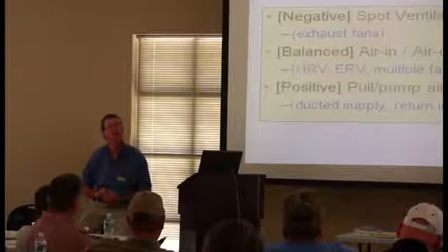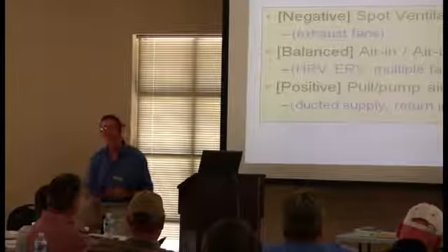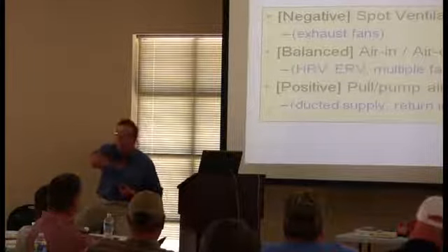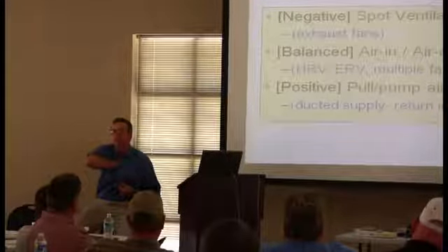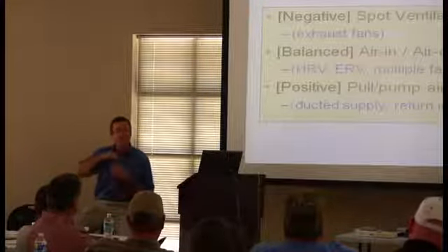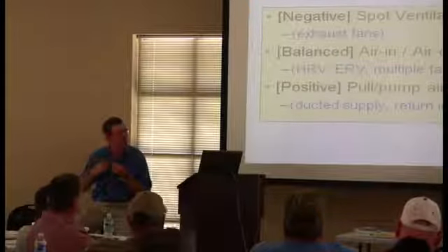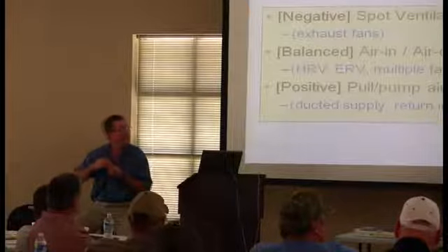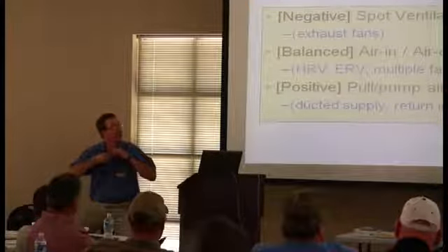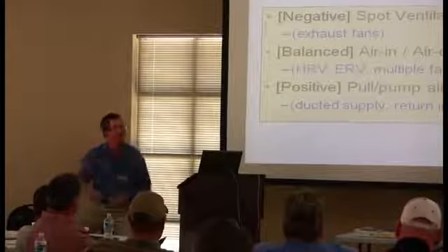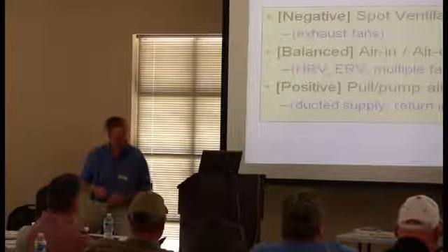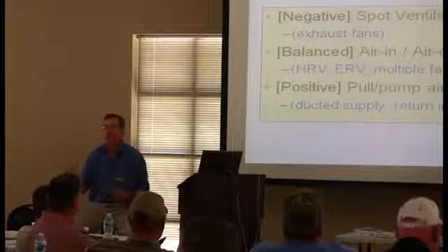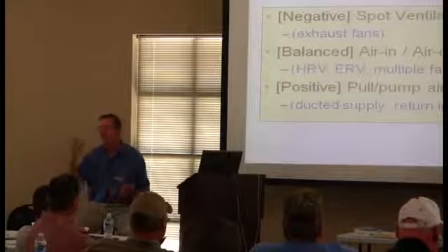I don't know why that is doing that, but if you lived in a humid climate like Georgia, why would you not want your house to be under negative pressure all the time? Oh, he said it. What's the answer? Yeah, if your house is always negative, then you're essentially pulling moisture in, from wherever all the time. That's the danger part. So if you lived in a humid climate, would you rather have your house be slightly negative or slightly positive?